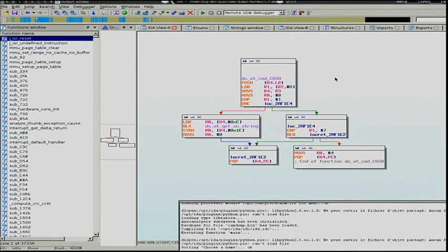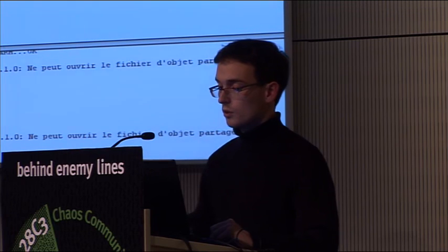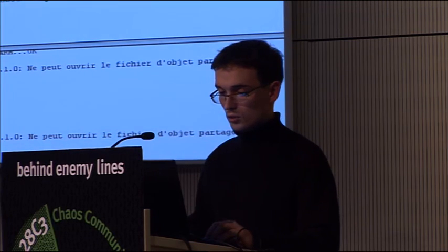So here is just an AT command handler for the CGSN AT command. It's just an AT command to get the IMEI of the phone and the serial number of the manufacturer of the mobile. So well, just putting a breakpoint on it.